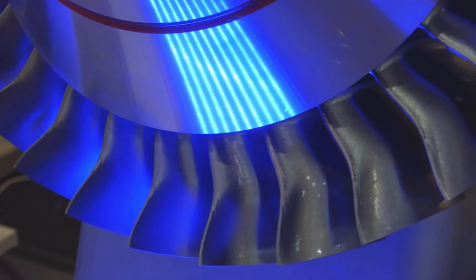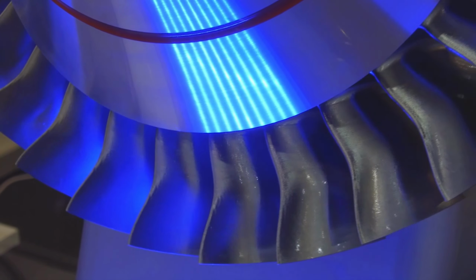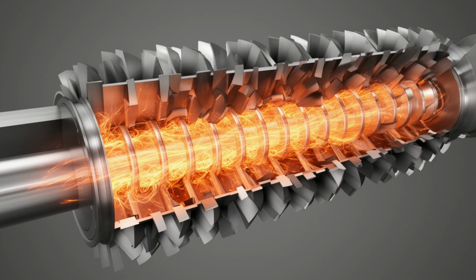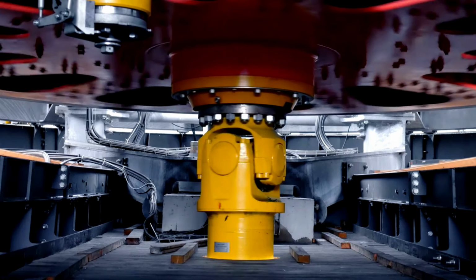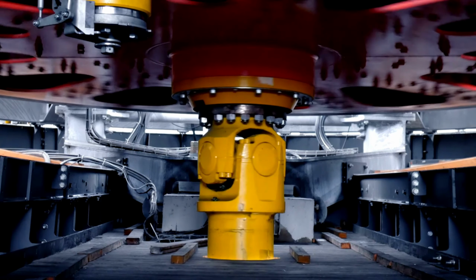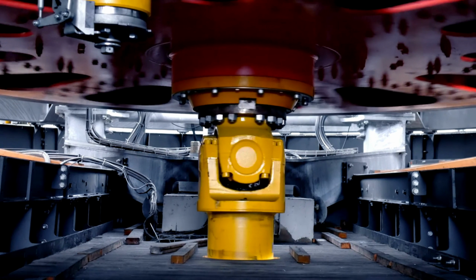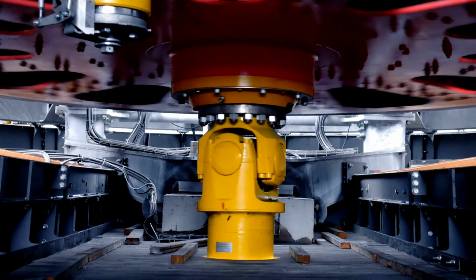This high-temperature, high-energy gas is directed into the turbine section. As the gas expands through rows of turbine blades, it transfers energy to the rotating shaft. The turbine extracts enough energy to drive the compressor at the front of the engine, ensuring continuous airflow. Any remaining energy becomes useful mechanical output. In a power plant, this output is what ultimately generates electricity.